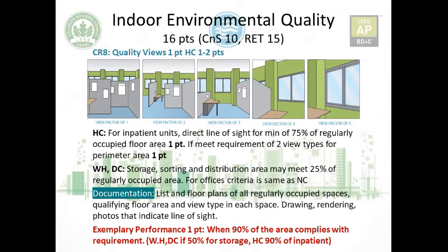Now for the documentation, since it asks you for regularly occupied areas, you have to submit the floor plans and qualifying floor area, what kind of view type you are designing for this space, and drawing, rendering, and photos that indicate line of sight. Now this drawing and rendering, of course, will be in the design phase. So if you have put it in the design, it will be easier for you to submit for the documentation.